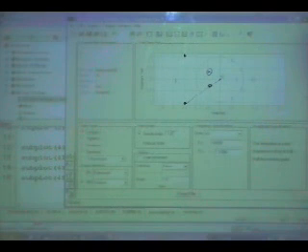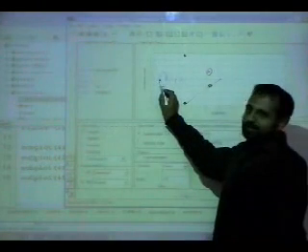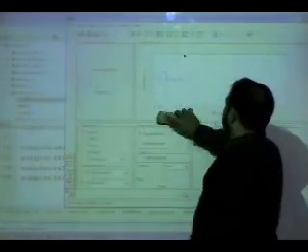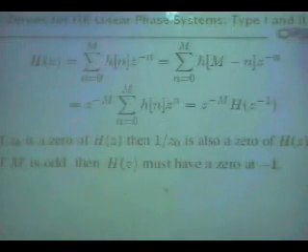If I ask you this is type 2, then you know there has to be a 0 at pi. Okay, a 0 at pi. There will always be a 0 at pi, because you want to design a linear phase FIR filter. Linear phase FIR filter is like this. So we know this now.